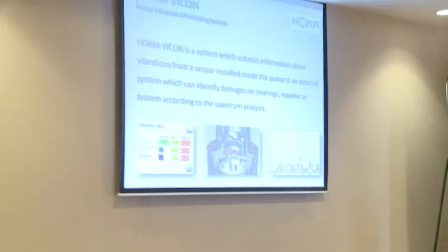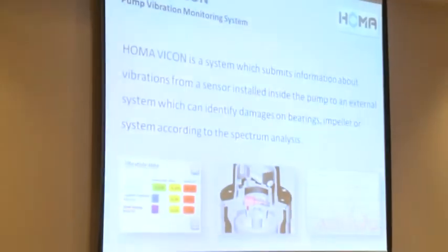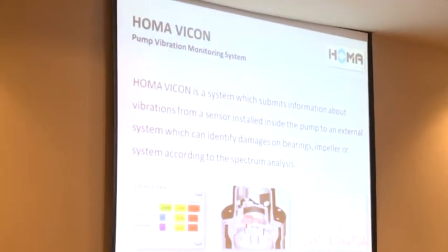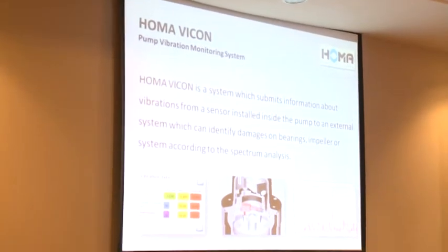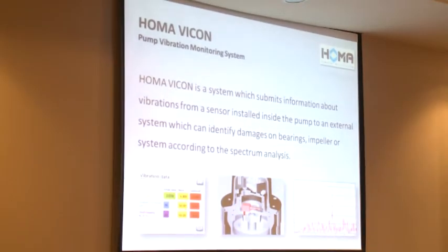As I said, regarding monitoring the operation, there's a possibility available on the market which is not only a vibration sensor inside of the pump, but rather a system to monitor the operation and give you a pre-alert, an early alert for a possible failure that might come up in the near future.